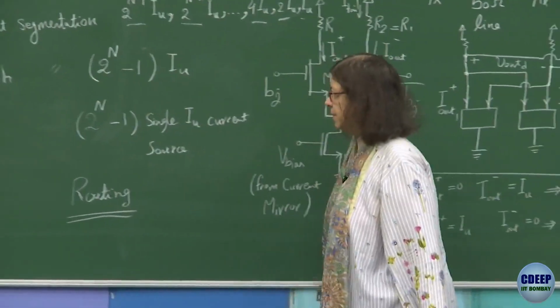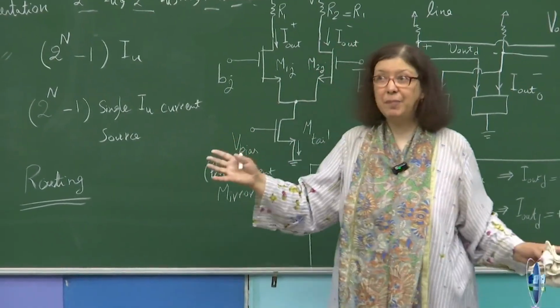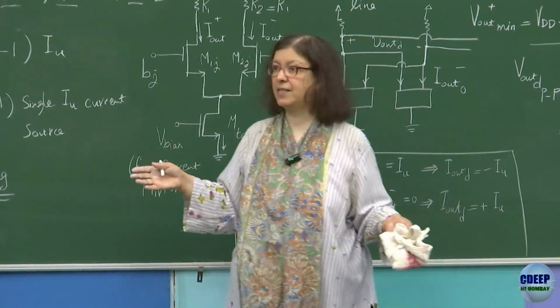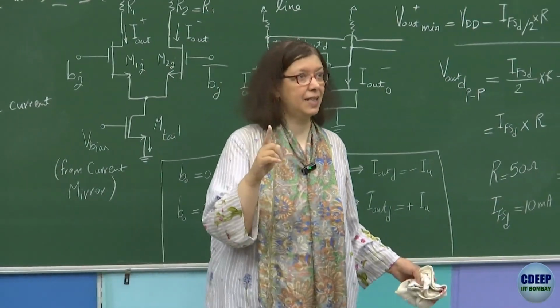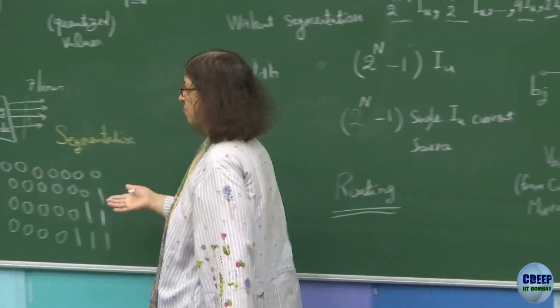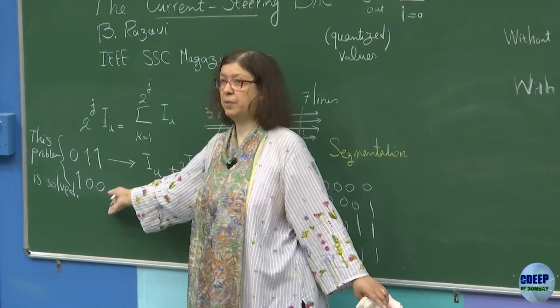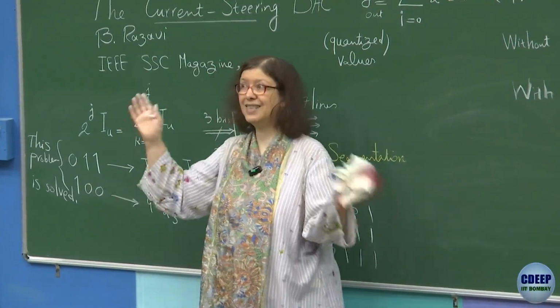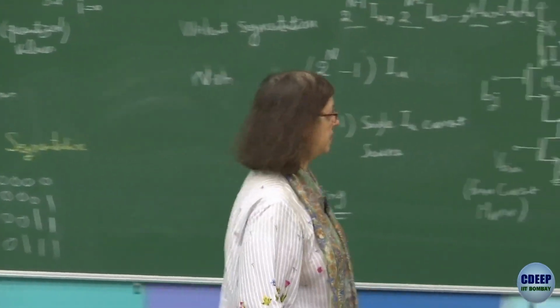Another advantage is that because there is only one bit changing at a time, cross-coupling and crosstalk effects will reduce at such high speed. In the previous scheme, many bits were changing at a time. Therefore, here even routing will be more of a problem, because you need to make sure that there is no crosstalk between the lines, between the bits.